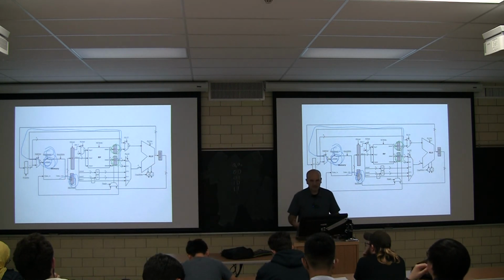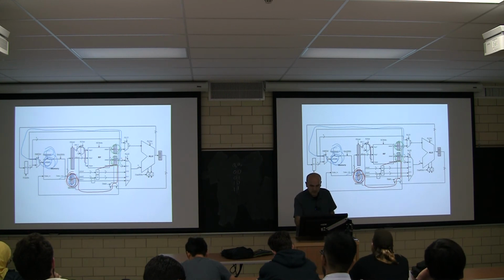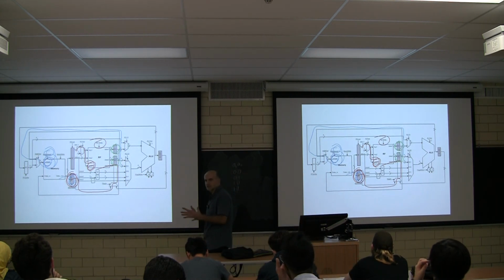So that was cycle 3, right? End of cycle 3. Cycle 4, we go and we write into the register file. So we take this guy through this wire over here. We're sending to the memory data port for writes. We're using the R1 name, using the upper part of that multiplexer as the name, and we say RF write. That's load. Done. 4 cycles. Same thing as loads, so add, subtracts, NAND, shifts.